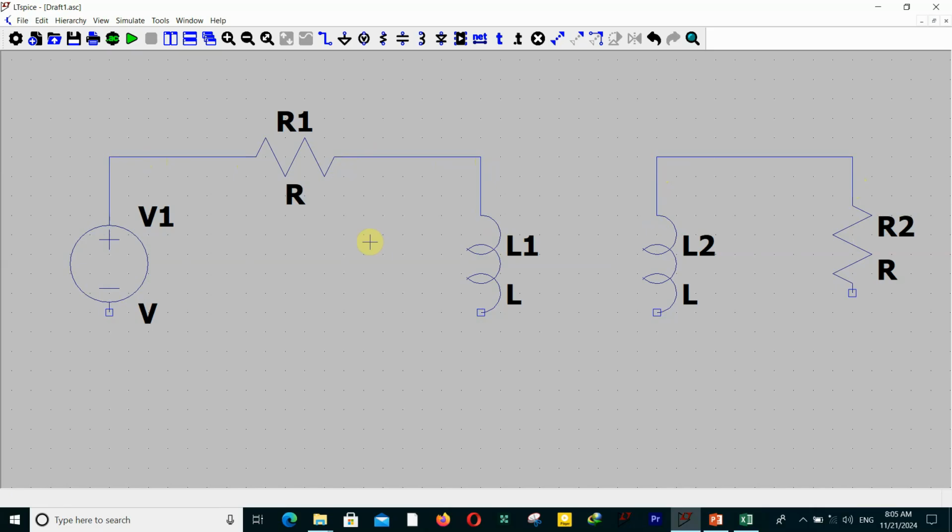I think this is the latest version of LTspice right now, and the hotkeys are a little bit different than the older versions, because in the older versions F3 was for wiring, but this is really close to what we have in PSpice or in Altium, where I think we use Ctrl W to wire some elements. Hit G for grounding your circuit.